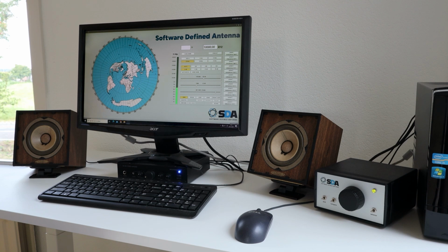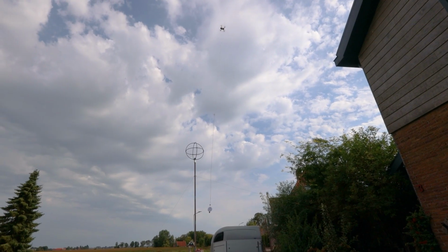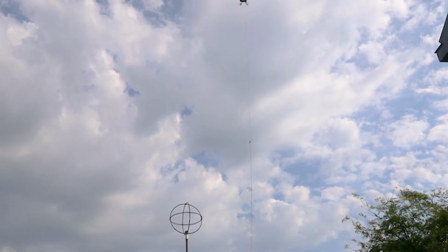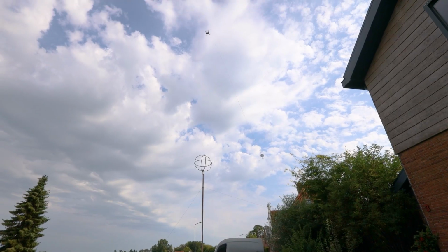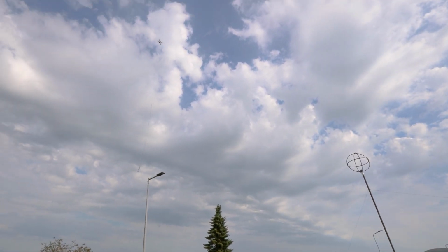A calibration beacon should be positioned at 3 or 4 different positions. One after the other, the beacon is measured while the position of the beacon in relation to the antenna is known. For this demonstration, the beacon is fastened under a drone so that several positions can be reached easily. The drone is brought in place and the beacon is lifted. The beacon is kept at a height of approximately 5 to 10 meters above the antenna height. With a curve, the drone goes on its way.